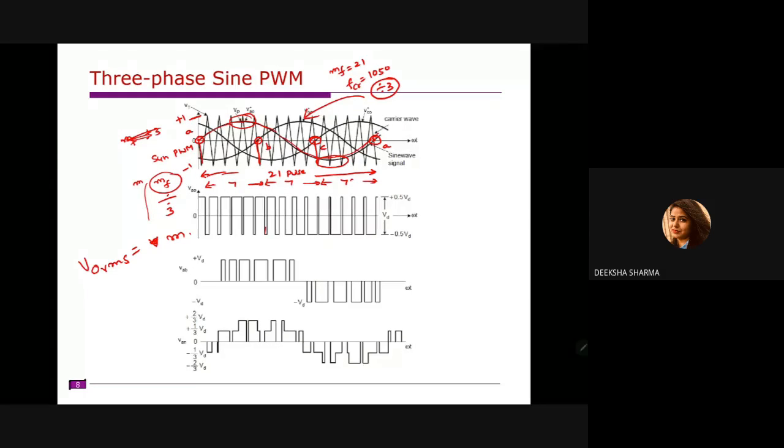So this is MA sine omega t. So this is the per unit value. The per unit value of this RMS voltage is related to this MA sine omega t, right? If you want to change the MA value, obviously the modulating signal changes. So both are in per unit relation, because here the MA is changing from +1 to -1. Therefore, this V0 RMS value also changes in per unit from +1 to -1. Clear?